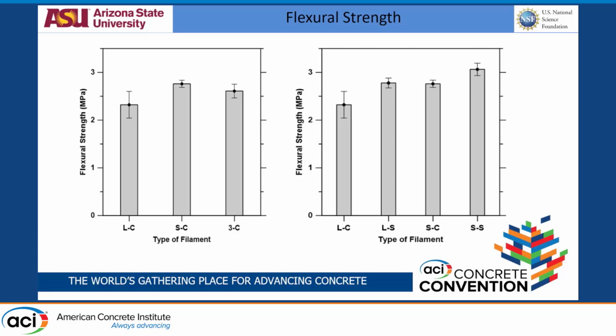So for the linear conventional, we got around a 2.3 MPa flexural strength. With the same system, when you curved it into an S-shape, we got around 2.5, 2.6. That's like a 20-30% increase in flexural strength without having to do any modification to the system at all. It's just the print method; the filament being printed is slightly altered. So just by that simple modification, without consuming more time or more material, we are getting a higher strength. That's significant, because why not get higher strength rather than lower strength from the same system, right?